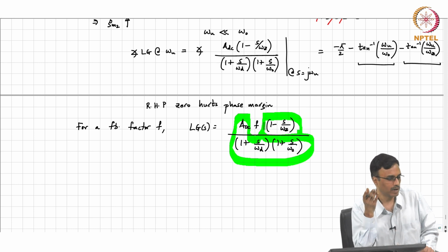If you are trying to build a voltage amplifier, 1 plus R2 by R1 type system, it is 1 over f, correct. And you want to build an amplifier, so f must be less than 1, correct. So, the useful range of f is 0 to 1. If you want to choose f equal to 4 like he suggested, the closed loop gain is 1 over 4. If you want to get 1 over 4, I think there are smarter ways of doing this than using an op amp, correct. So, the feedback factors we have to worry about are basically f ranging from 0 to 1, right.